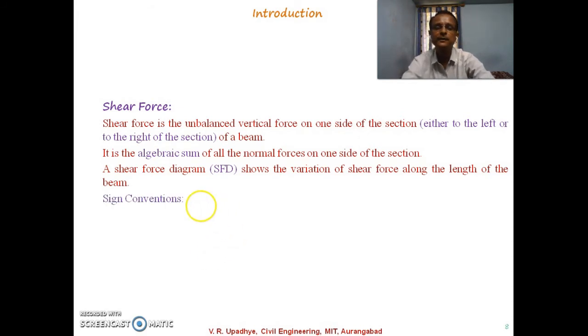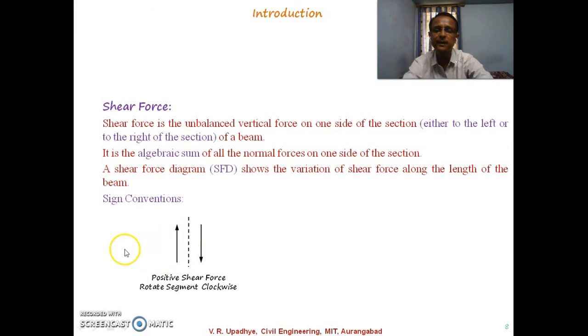Generally, for the analysis of shear force, the sign conventions used are something like this. Suppose I am considering a section somewhere over here, and we are considering the left part of the section and the forces acting on the left part of that particular section, then the upward forces will be considered as a positive shear force.